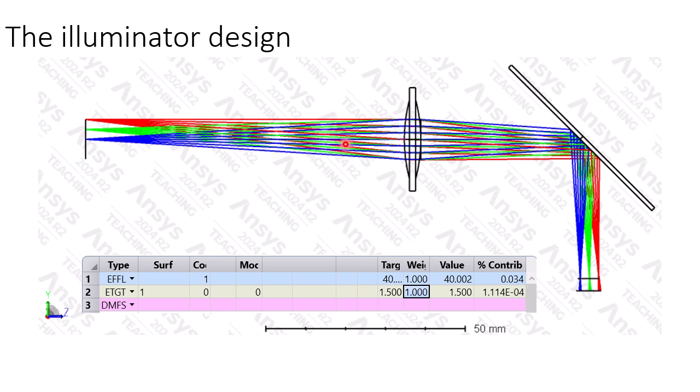We have here our lens, which I've incorporated some little lips on the edge so we can fit it in our housing. This is a 40 millimeter focal length lens. That's what I've specified. And our object is spaced 80 millimeters from our lens. So I've kept our illuminator under that 15 centimeter threshold.